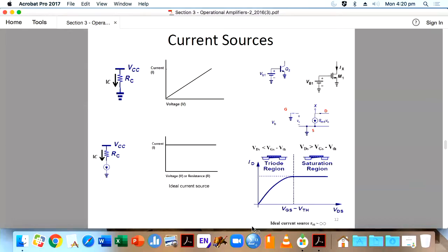You will be seeing low frequency and then so many frequency components, even very high frequencies, and only then do you get a 10 nanosecond pulse. If you remove some of the high frequencies, then what will happen? You are going to put this through a low pass filter, so you are removing some frequency components. Then maybe it will become 100 nanoseconds because you already removed some frequency components. If you further remove, again it will spread. So this sharpness or the width depends upon how many frequency components you got. If you got infinite frequencies, you get a delta function. That is not possible. That's the concept.